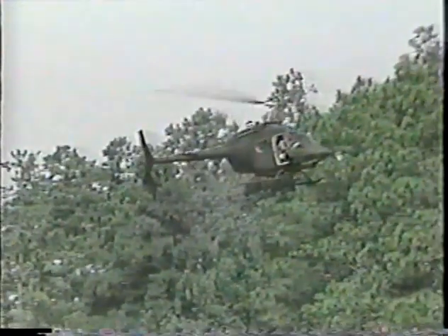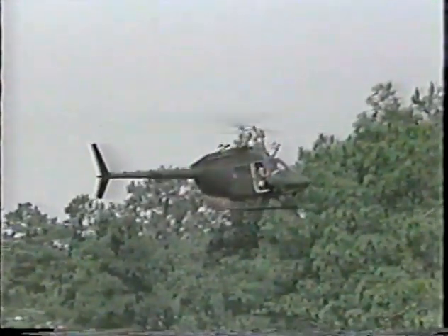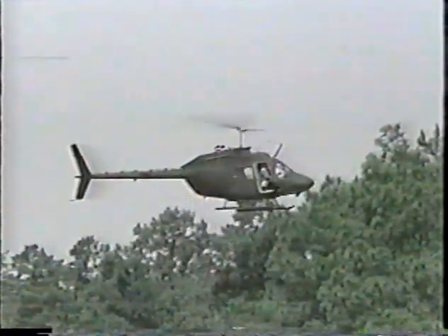The pilot's major concern in this area would be the weather vaning capabilities of this crosswind. The wind is strong enough to force the aircraft into a left yaw, which the pilot must correct with right pedal. If the application of right pedal causes the aircraft to yaw right to where the relative wind moves into the weathercocking region, the yaw can rapidly progress into a spin.